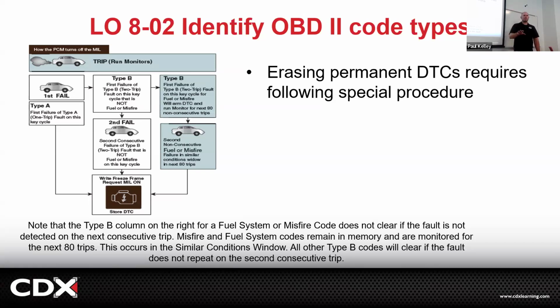If the misfire is fixed, guess what happens with that monitor? Not the MIL, the actual monitor, the test. If it's fixed and it runs the test now, what's going to happen? It's going to pass. When it passes, the MIL goes off. You have to actually fix it, and you have to actually get it to run the monitor, and the monitor passing will turn off the MIL.